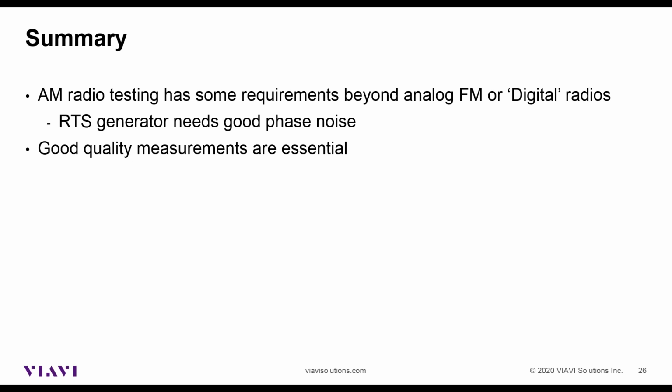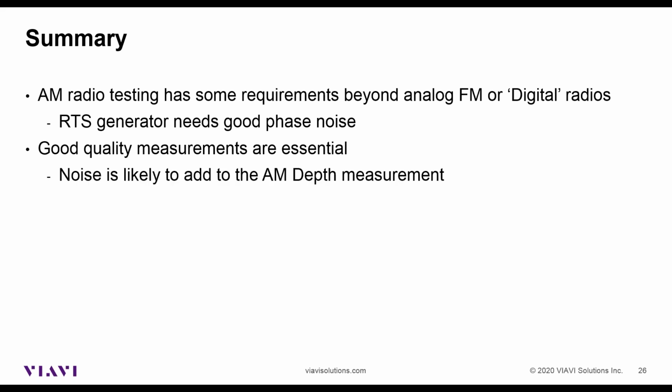Good quality measurements are essential. Again, if we're switching different IF filters, for example, or audio filters, our filters are digital now, they're perfectly flat. In the 2945, as a good example, the filters were real resistors and capacitors. So when you switched those filters, you had uncertainty in the switch, if the contacts were aged or not very clean, and also tolerances in the components. The filters these days are all software, they're perfect, as opposed to the old days where they were a few percent out because of tolerances on the components.